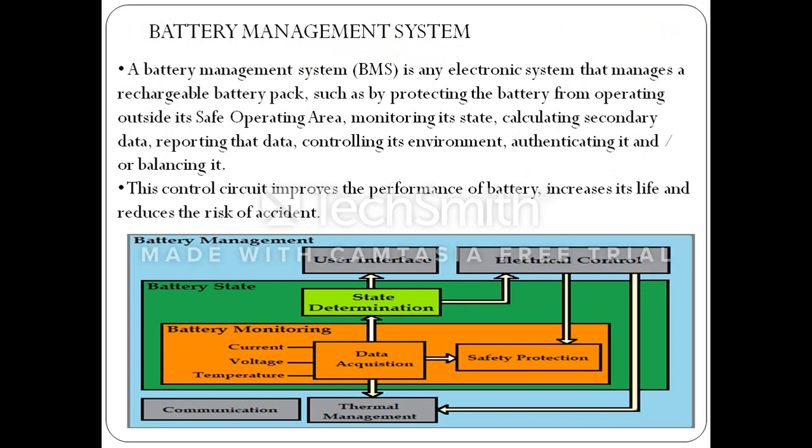Then what is a battery management system? A battery management system, that is BMS, is any electronic system that manages a rechargeable battery pack, such as by protecting a battery from operating outside of its safe operating area, monitoring its state and calculating secondary data, reporting that data, controlling its environment, authenticating it, and balancing it.